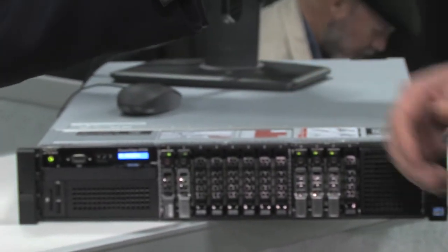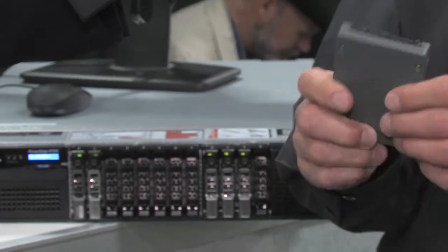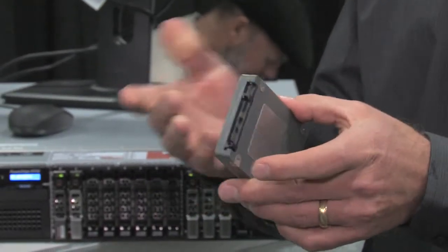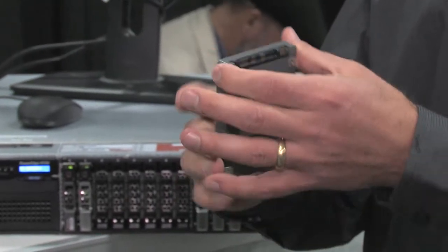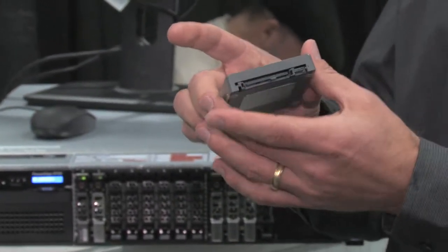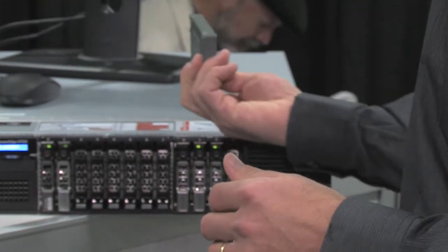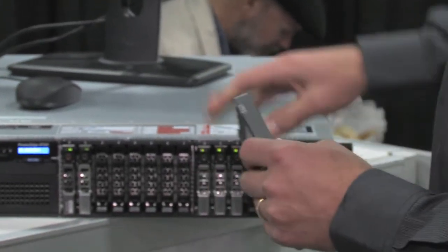The ecosystem includes drivers that are open source and available today. Those would be for Linux, Windows, with UEFI drivers in process. Several different drivers are in process as well. And then we also have over here a server that supports PCI Express at the front of the box. This here is a prototype device, and it's got a connector very much like your typical SAS or SATA connector. The difference though is it has PCIe lanes. It's got 4 lanes of PCIe that can connect into the PCIe root complex.